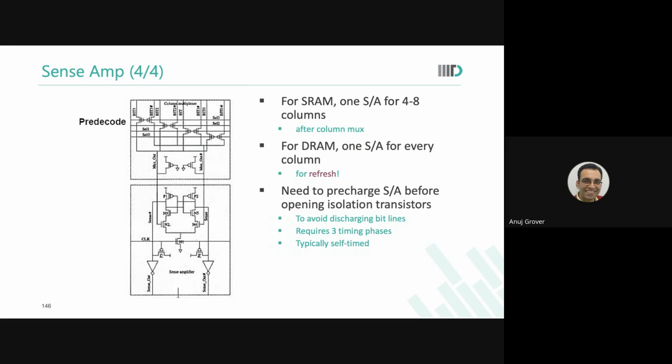For example, when I designed the sense amplifier, my goal was to be able to move from 0.3 volts to 1.2 volts. At such a wide range, device-based capacitances would have nonlinear behavior. For me, that was unacceptable. So I used a metal-based capacitor. You could also design those capacitances through devices. Is that okay? Anything else?